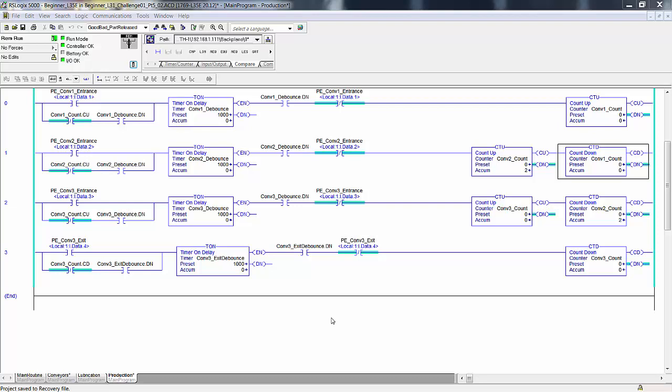Energy requirements are yielded in this phase, and especially the sensors and the actuators to sense and operate the mechanical design. Again, you need 3D visualization. A good mechanical machine process designer will have a controls engineer involved during this phase to influence the mechanical design to accommodate specific sensors and type of motion, i.e. cylinders, AC motors, servo motors, etc.